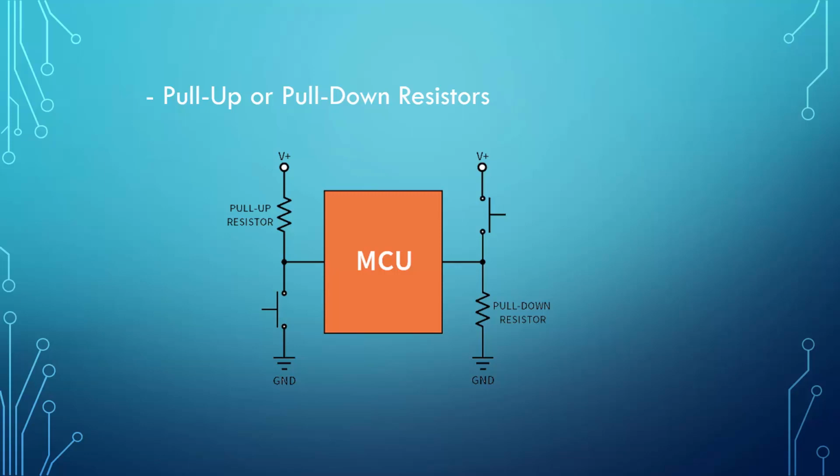Pull down resistors are less common than pull ups, but can still be useful, especially if you are dealing with a need for defaults to be low or ground. Pull-up resistors are often used when interfacing with a button or switch input. The pull-up resistor can bias the input pin when the switch is open, and it will protect the circuit from a short when the switch is closed.